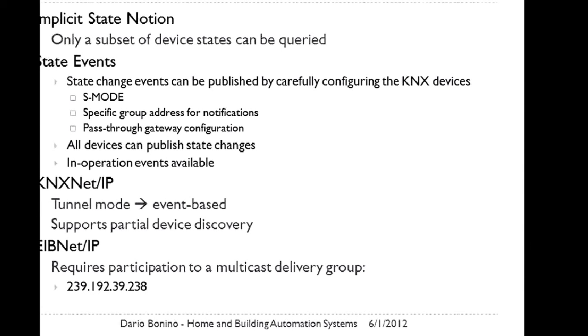Because we can have state changes only if we use the software for configuring the devices and handling the extra binding needed for a state change. And we need to be really careful in the configuration because we need to define proper group addresses, one for each device we want to listen to. Okay? So we are wasting group addresses for listening to state changes.